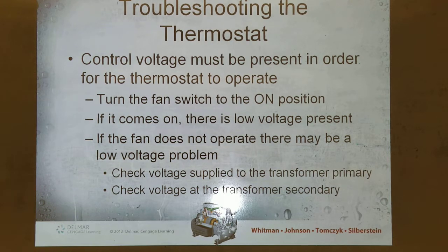In fact, I was gonna write a book about shortcuts like this, and this is just a shortcut. This is telling you, first thing you do, what's wrong with the unit? You don't know, customer's not around, what's going on with it? Where do you start? Go to the thermostat. That's what it's saying, right? Go into the thermostat, hit that fan switch. Does the fan come on?